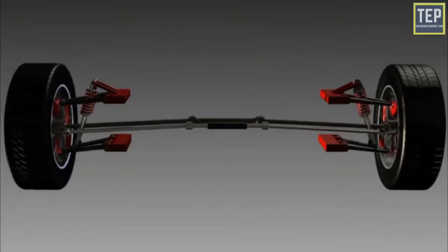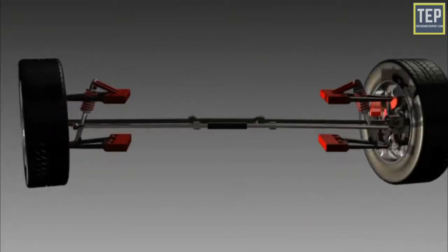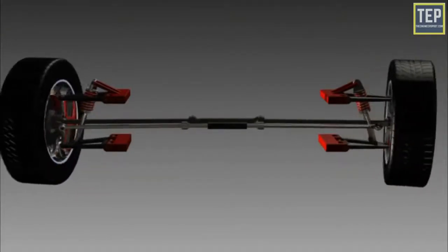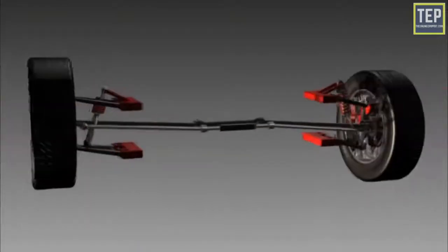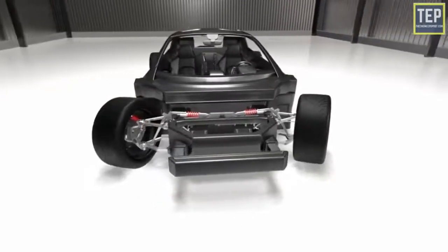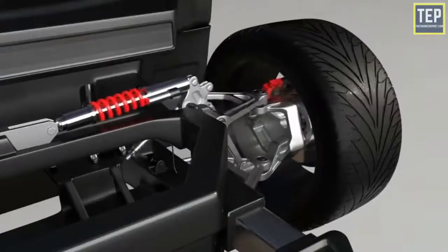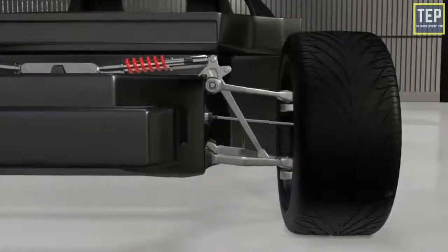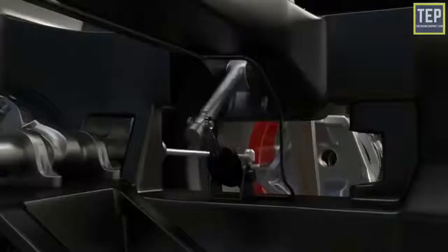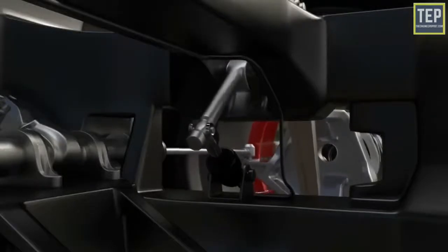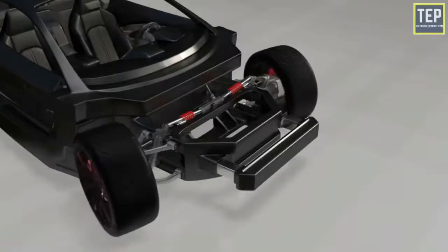When the vehicle moves on uneven surfaces, the wheel faces shocks. These shocks are transferred to the shock absorber through the lower link. The shock absorber absorbs the maximum amount of shocks. The upper link is used to maintain the camber of the wheel. This system is complex, as well as costly, and it requires more space.